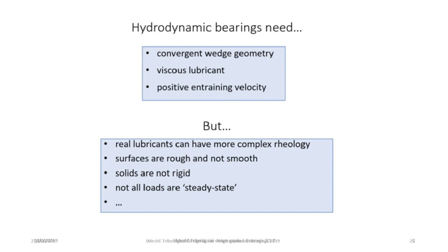The situation will also be more complicated if the load is non-steady, but varies in either magnitude or direction, or perhaps both. The behavior of the film is still essentially governed by Reynolds' equation, but now relatively simple analytical solutions are no longer possible, and we must seek numerical solutions. These are beyond the scope of these introductory ideas.